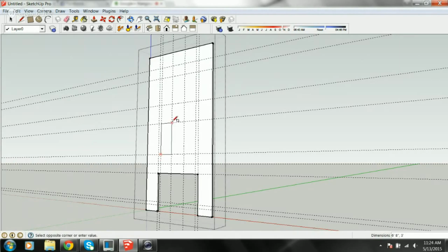So again, rectangle, rectangle, come up here, push, pull. I'll hit 3 just to be safe. When it says on face, for those that aren't familiar with modeling, it's reading the back face of this plane right now. Sometimes you won't see anything. You'll push, you think you're even, but nothing disappears. It actually pushes through the back of the wall and creates an object on the back side of the wall.